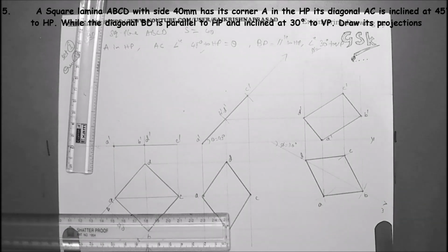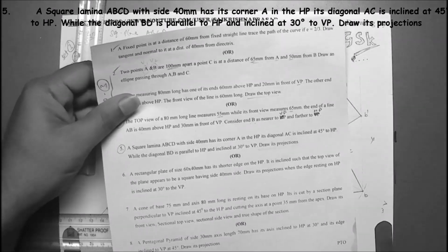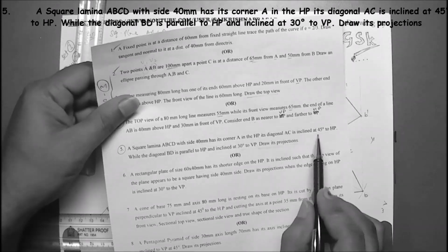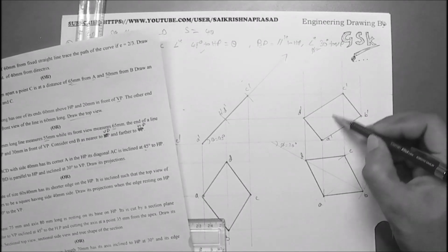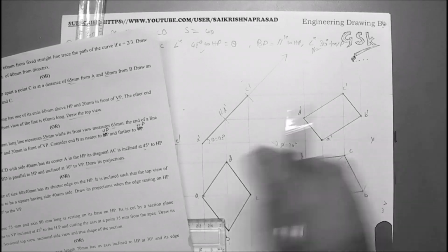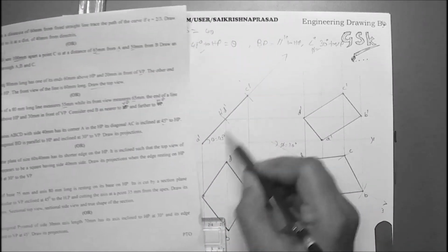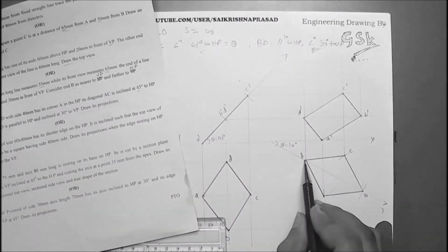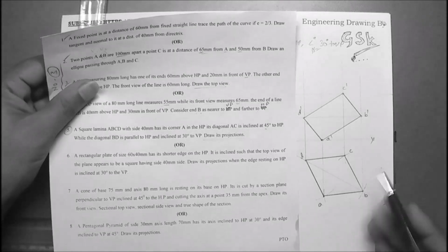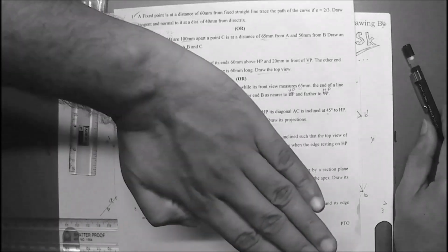Now see here, coming to the question, it is given that diagonal AC is 45 degrees inclined to the HP. Same figure is coming over here, right? AC is 45 degrees inclined to the HP and BD is parallel to HP. BD is parallel to HP, and means height. If this is the HP, BD would be like this.